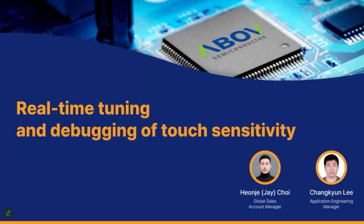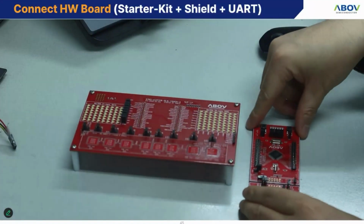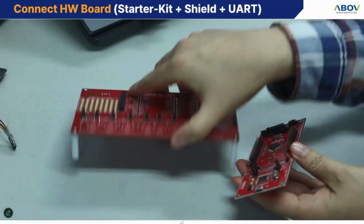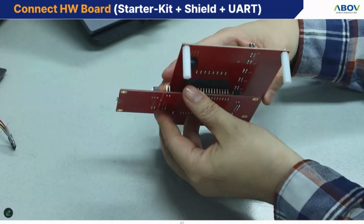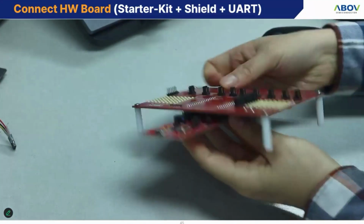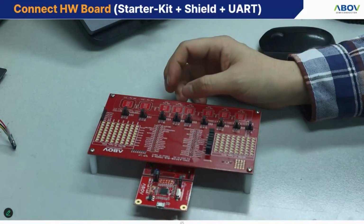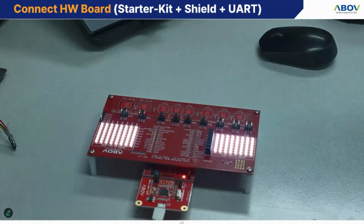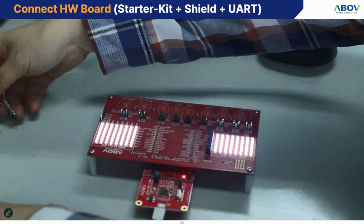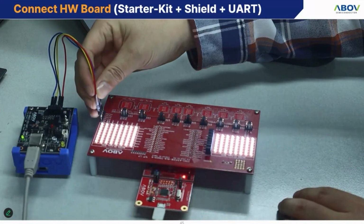Okay, then I will switch to real-time tuning and debugging of our touch MCU. For basic touch testing, you should connect starter kit and shield board. And then use a USB cable to connect to your computer, and also to use the graphic user interface. You should connect the separate USB to UART board to the RX and TX pins of the shield board.